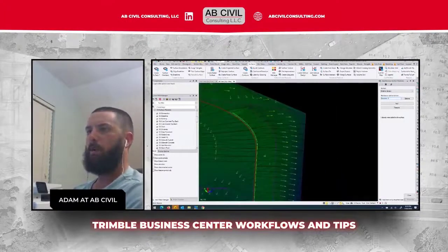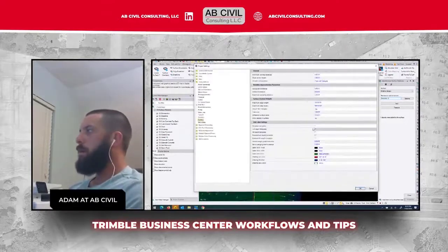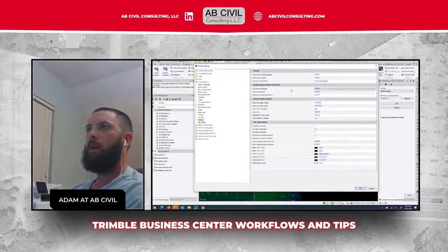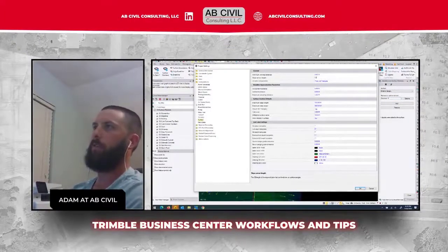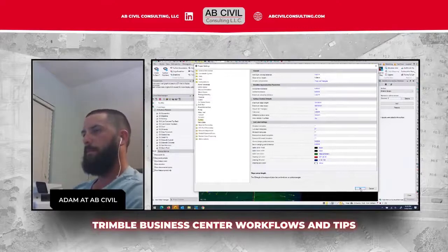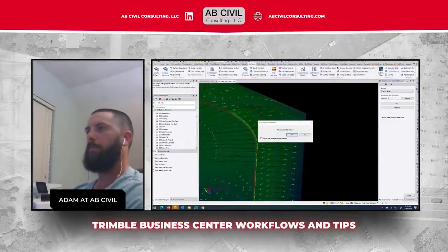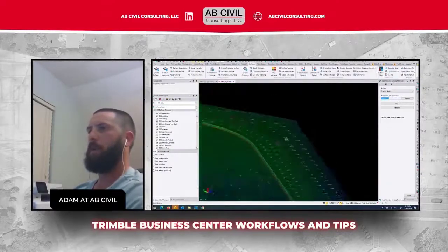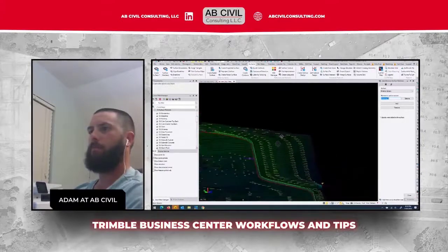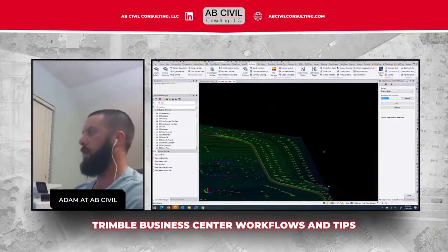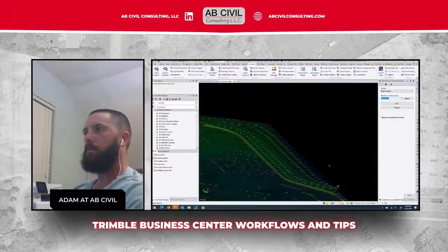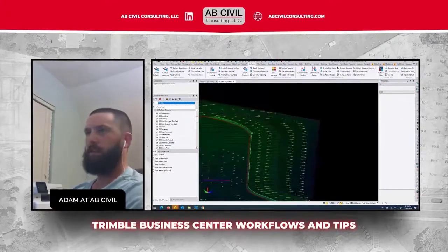And then the reason these slope arrows aren't showing up is because these triangles are too tight. We go to settings. In this case, I'm just going to change the slope arrow length to 1.5 feet. Should do it. So now you get your sidewalk draining down towards your curb, and then it automatically sloped everything right off back to the outside. Did that answer your question, Alex?